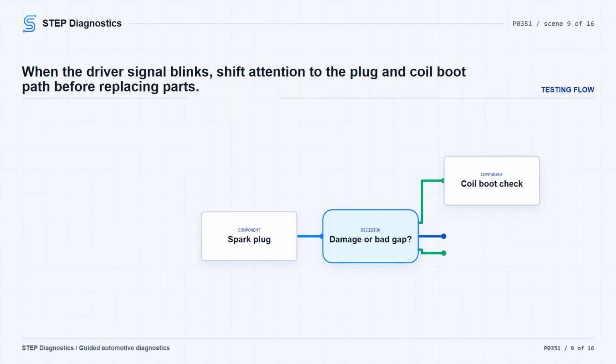When the control circuit gives a bright blinking signal, turn the ignition off and remove the related spark plug or plugs. Inspect for cracks, carbon tracking, foreign material, gap size out of specifications, and a loose or broken electrode. If any of those conditions are present, replace the spark plug.